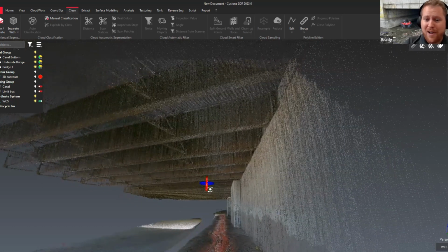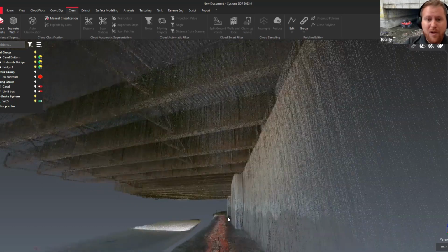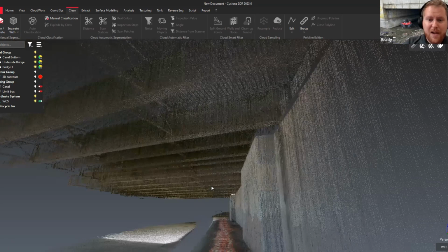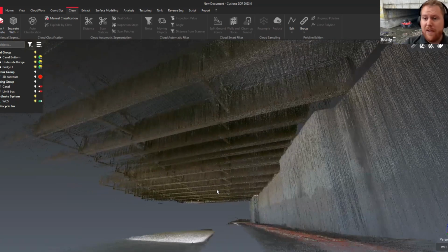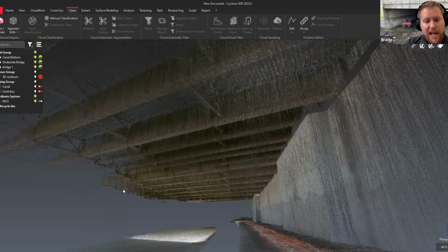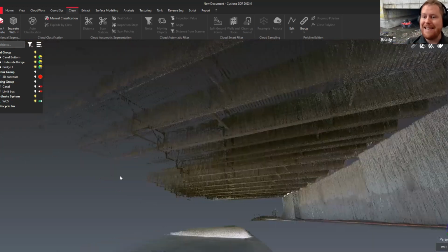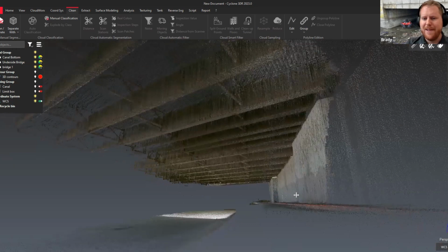So you can see just walking the animal straight down and straight back, we've got great data coming out. Now, as I mentioned, the 25-meter range, we can see we started to capture towards the other side, but we didn't capture all of the other side. So ideally, if this was going to be walked for permanent record, we would take the animal down to the bottom and we'd do several scans up and down and scan more of this information to then complete this bridge and this storm drainage canal, if that makes any sense.